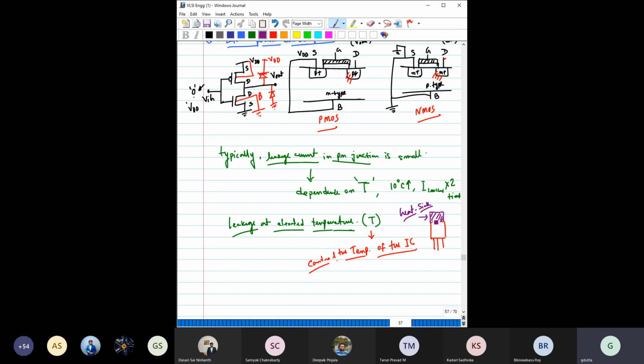One of the important techniques is just to use a heat sink. Here you connect a big metal piece compared to your IC, so basically you are increasing the area. That will dissipate the heat in a better way and try to balance the temperature inside the device. In some cases, the addition of the heat sink alone is not enough. You need to cool it externally. So maybe you have seen in some ICs they have given a fan, an external fan, which is basically for cooling. In some cases, they flow some liquid inside a microfluidic channel to cool down the total IC temperature.